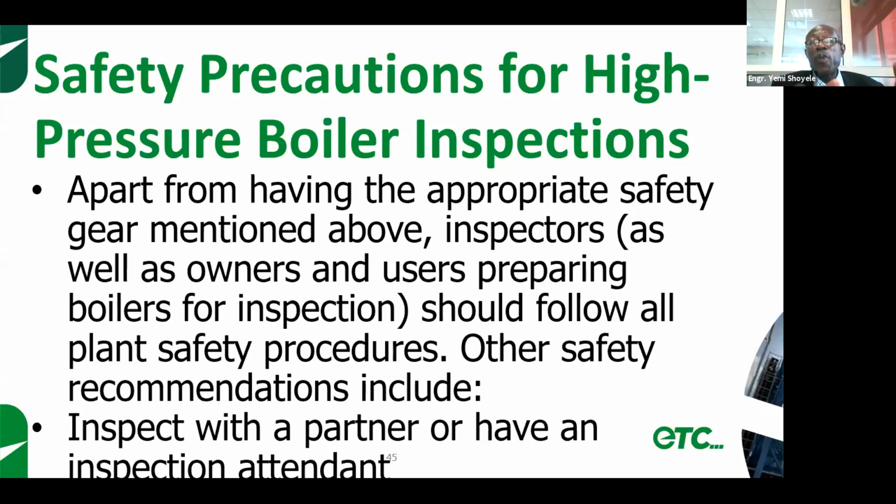And especially again for fire tube boilers, you should have something like a safety harness. We used to call it in those days monkey ropes, tied to the guy who is in the water side of the boiler. You remember that on the water side of the boiler, you cannot stand, on the fire tube boiler, you cannot stand anywhere. You can only crawl on the water side at the bottom. And you need to do this for the annual inspection on the water side. On the fire side, you can stand inside the furnace or almost anywhere.